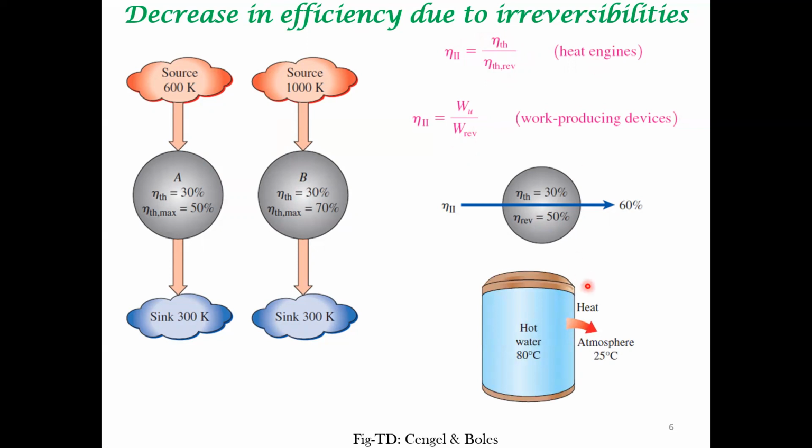When you transfer heat, as I said, across a finite temperature differential without passing it through a heat engine, then that is, in a way, the worst possible way to utilize heat. Okay, so you didn't get any amount of work with this heat transfer. So in some way that is the most ineffective heat transfer because you didn't get any work out of it. But sometimes in real processes, this might actually happen. Okay? All we are saying is that's not the best utilization of thermal energy available at a high temperature.